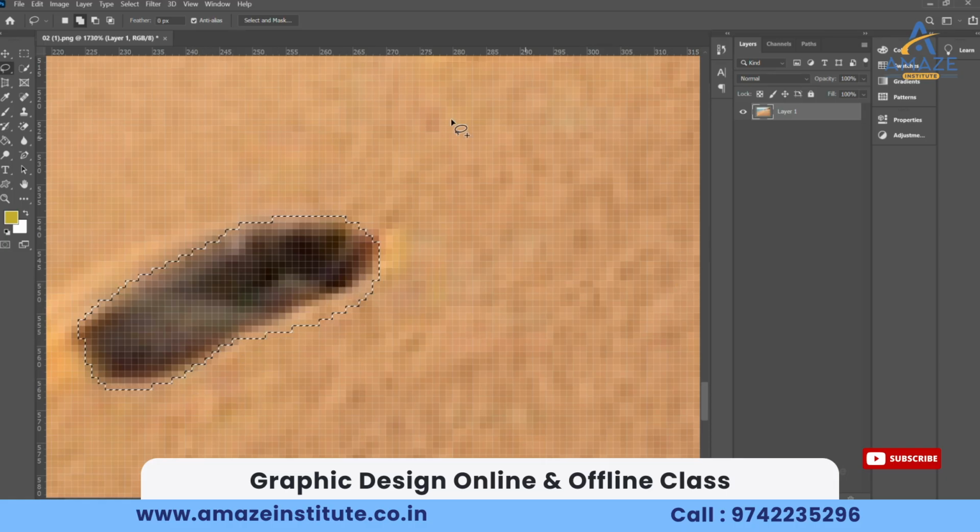So to deselect this portion, with the same lasso tool selected, I make it Subtract from Selection. If I click Subtract from Selection, what should I do? I should draw a line starting from outside the selection, drawing to this outline, and then come outside and close the selection. After that, this extra selection will be deleted. Now from outside, I'm drawing like this and closing like this. Now this is coming like this.